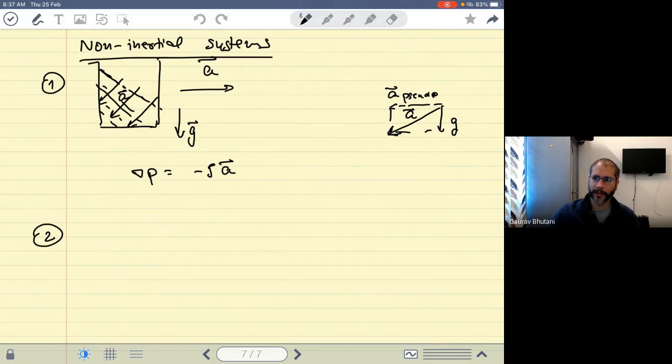All right, so the next common example that we have is rotation. And fluids undergo a lot of rotation, and in this case we are considering rigid body rotation. If you take a fluid and start rotating it and leave it like that for a very long time, initially the layers will start to move with respect to each other because of viscosity. But if you leave that for a very long time, then slowly the fluid will come to a rigid body rotation, that is V equals omega R.